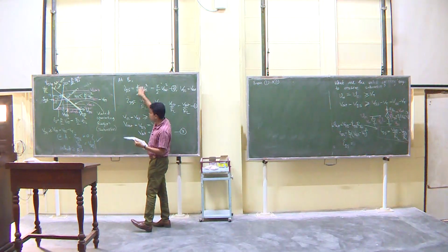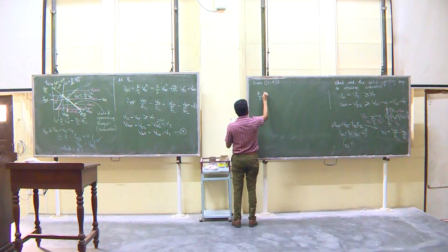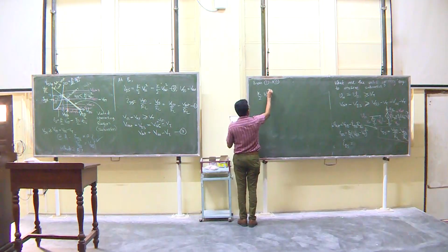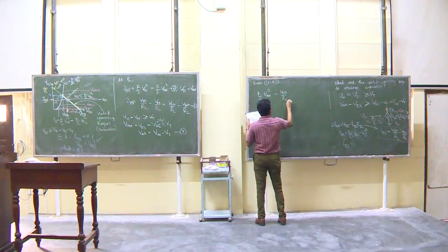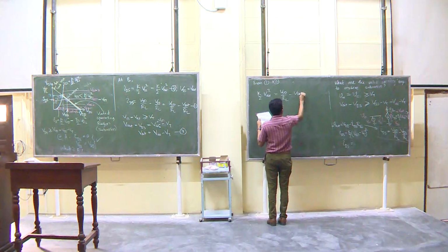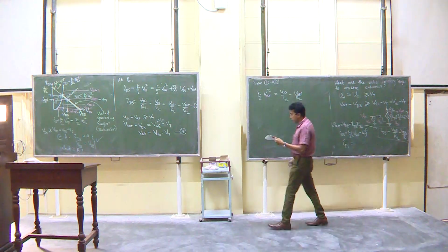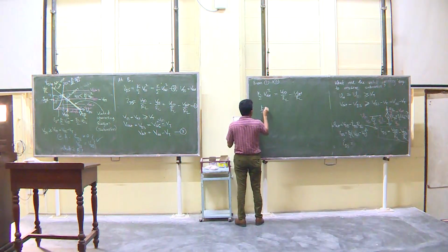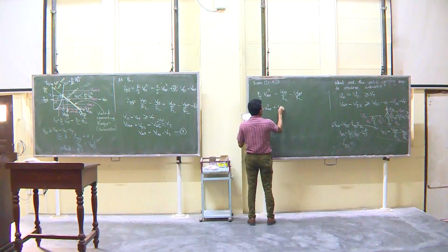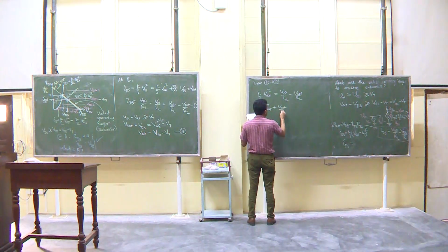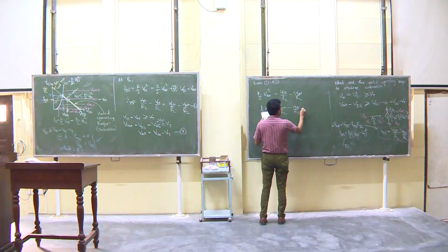Okay. I am going to put this right here, so that I will have K divided by 2 V out squared is equal to VDD divided by RL minus V out divided by RL. So, what you have here is a quadratic equation where you have K divided by 2 V out squared plus V out over RL minus VDD over RL is equal to 0.